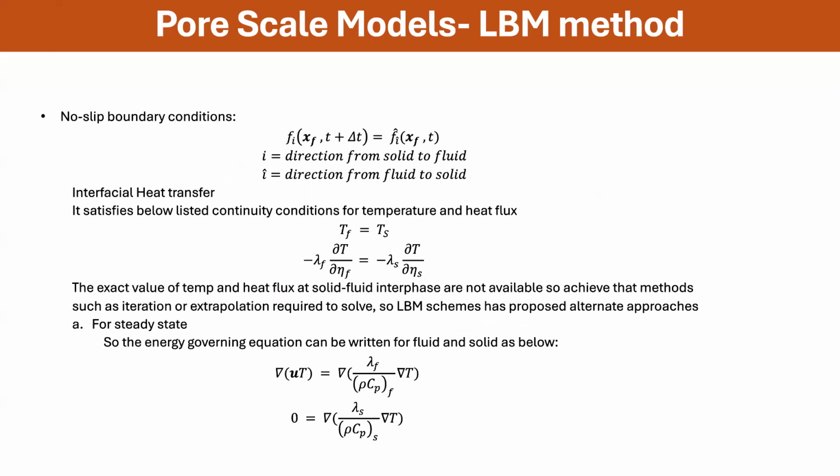As discussed in the class, this is the equation that is used for the no slip boundary condition. i is the direction from solid to fluid and i-cap is the inverse direction. Now for the second boundary condition, where there is heat transfer at the solid fluid interface, for the sake of understanding, what we are saying is that temperature is the same at the boundary for fluid and solid, and the heat flux as well.